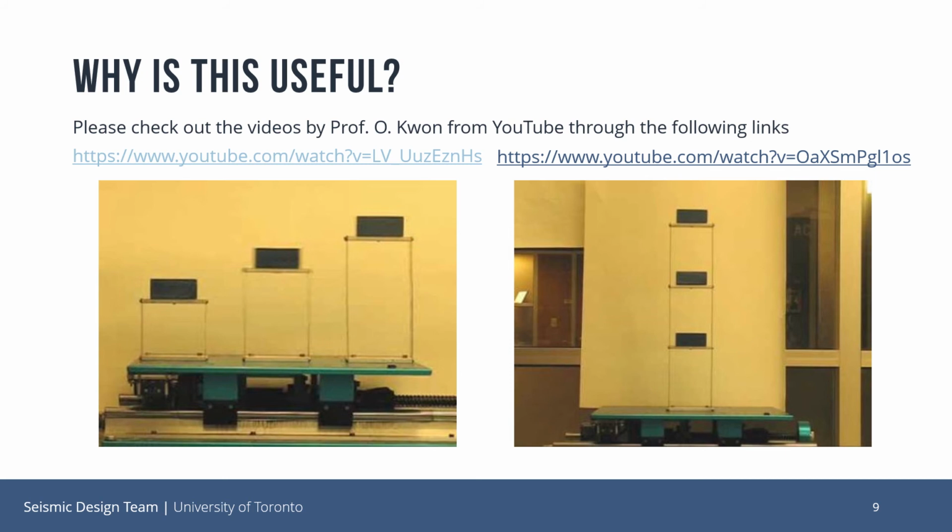Okay, cool, everyone's ready. All right, so now a similar idea, but this time we have a multiple degree of freedom system. You can see there's 3 different masses, which means there's going to be a couple different mode shapes that this building can have. As we go through and do the same sine sweep, so as we go through different frequencies of the sine excitation, you'll see different mode shapes happening at different frequencies, which is going to be pretty interesting.